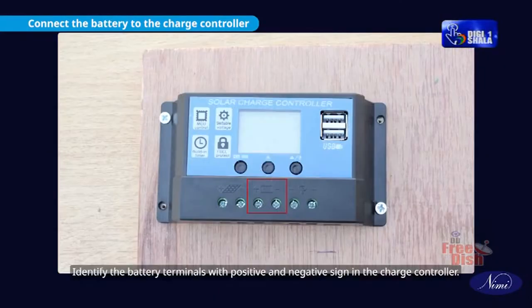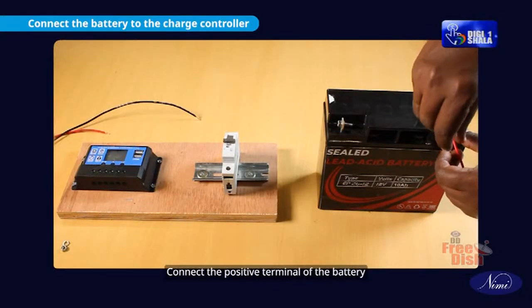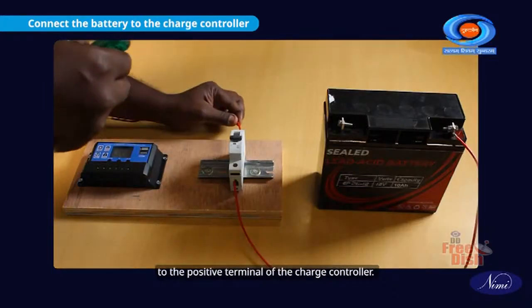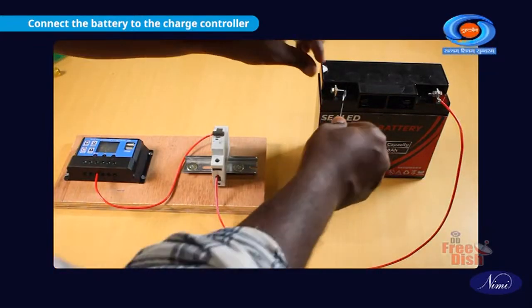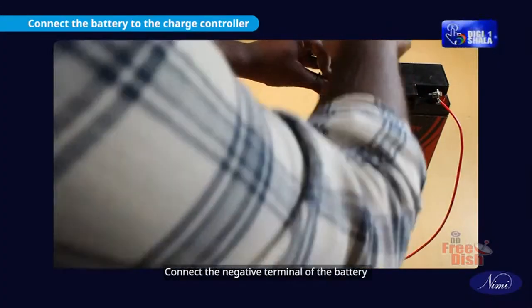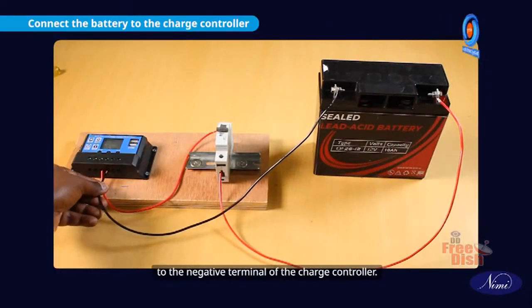Identify the battery terminals with positive and negative signs on the charge controller. The charge controller typically has labeled terminals for connection. Connect the positive terminal of the battery to the positive terminal of the charge controller. Connect the negative terminal of the battery to the negative terminal of the charge controller.